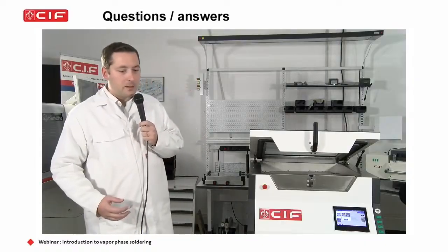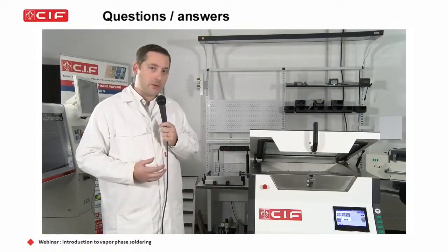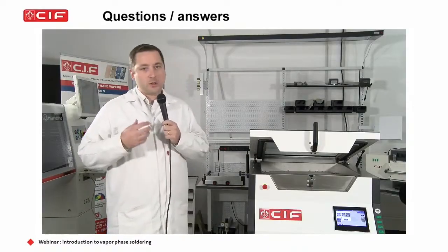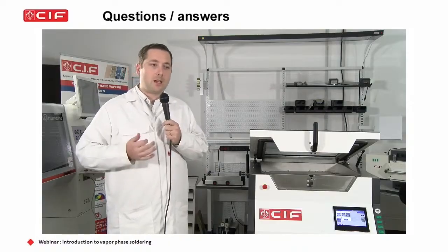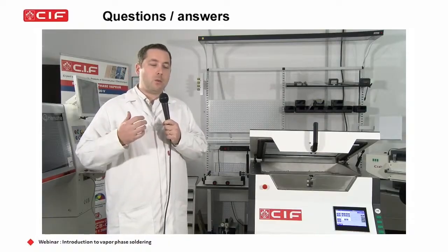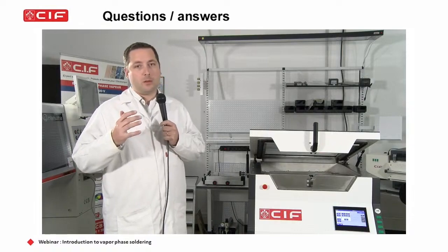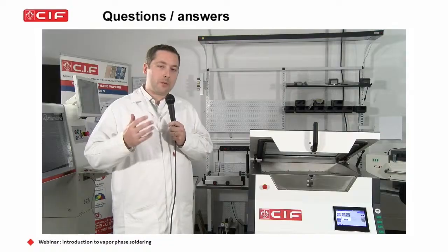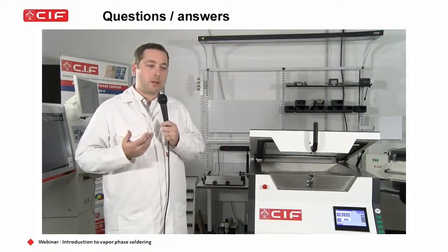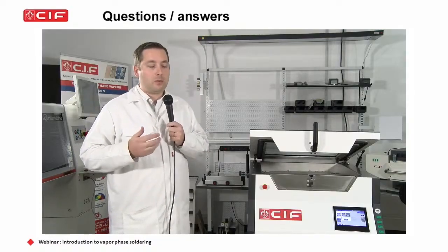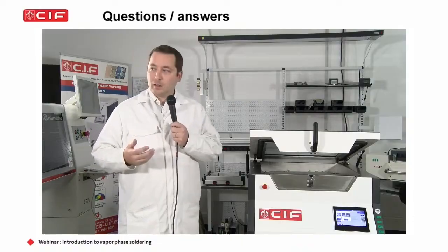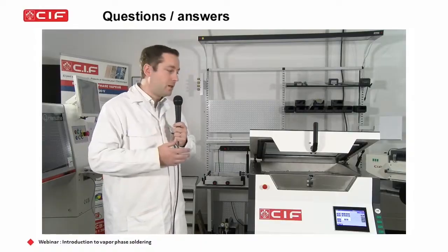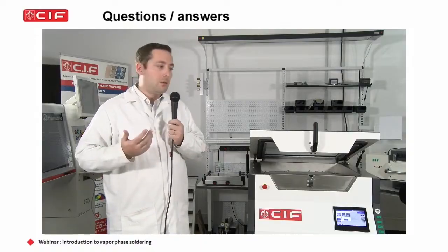The machine is not fitted with a Galden level gauge which tells you the exact amount that is remaining inside, but we are using the software to detect the lack of Galden inside, and once the Galden reaches a certain level, which is about 4 liters remaining, the machine will pop up an alarm to the operator to tell him to refill 1 liter at the end of the current cycle. So once you get the pop-up, you need to top up with 1 liter each time.